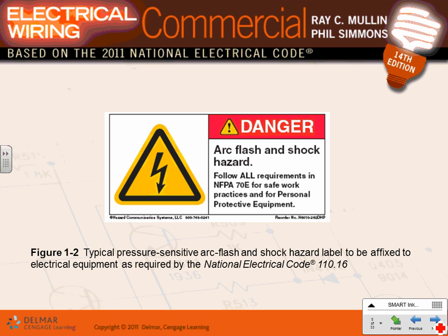It could happen. A bolt that you're holding in your hand drops. Anything could happen. When you push it hard, it fails and arcs. So a lot of things could happen inside the panel. So you need to be aware of this danger, arc flash and shock hazard, so you are required to have personal protective equipment, gear to protect you.